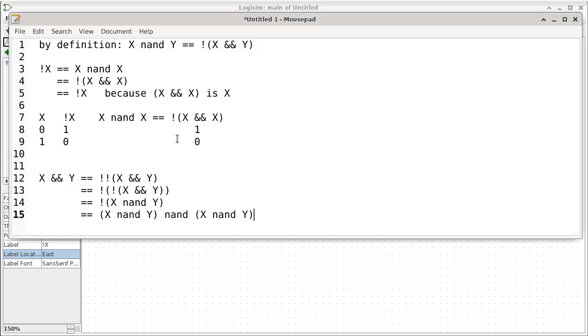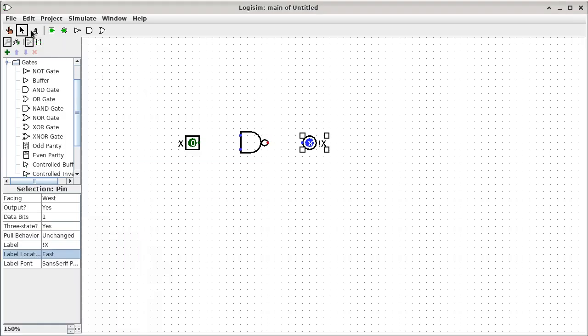We switch back to the expression, which is this one here. The gate is NAND, and we want the 2 inputs into the NAND gate both to be x, right? So when we switch back to the circuit, this goes to both inputs of the NAND gate. This one, and here's the other one. Is that okay? So now the NAND gate is taking x, which is the input, as both of its inputs, which is the equivalent of using x on both sides of the NAND operator in an expression.